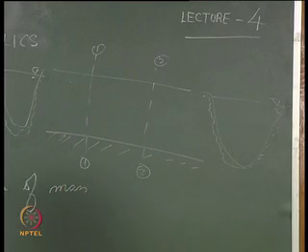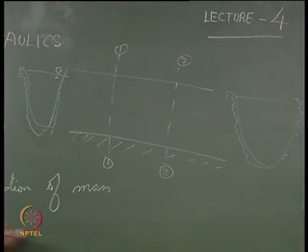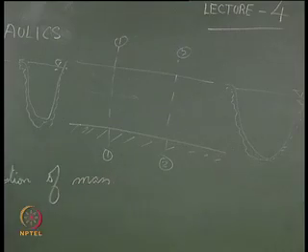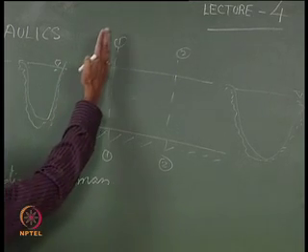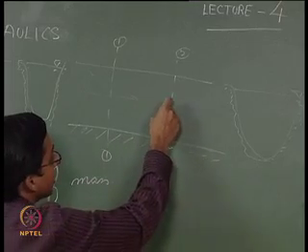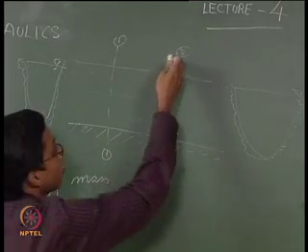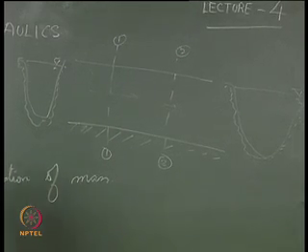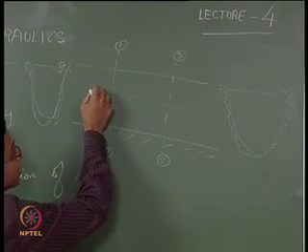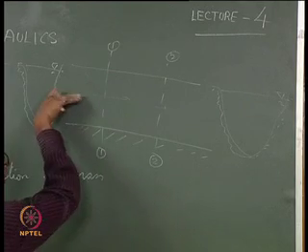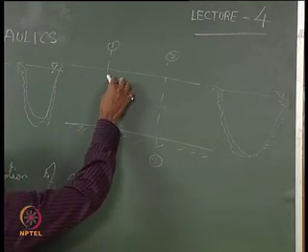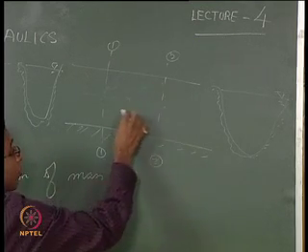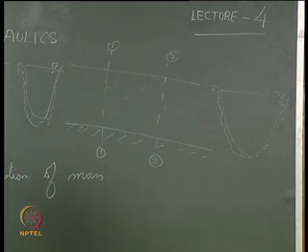Now, according to channel hydraulics, conservation of mass means that if the fluid is flowing in this direction, then the mass of water coming out from section 2 2 is nothing but the summation of the amount of water coming into section 1 1, plus the rate of change of mass of water stored between sections 1 1 and 2 2.